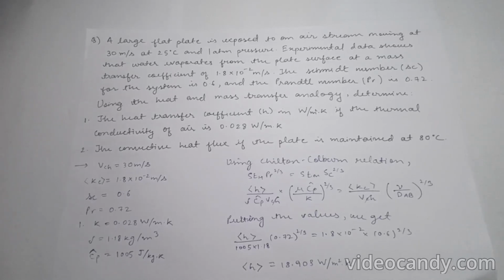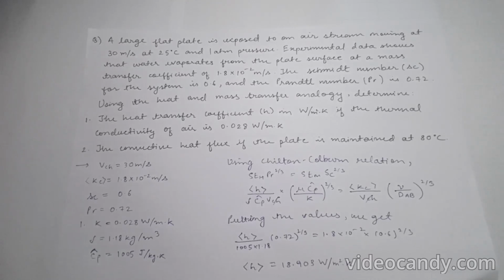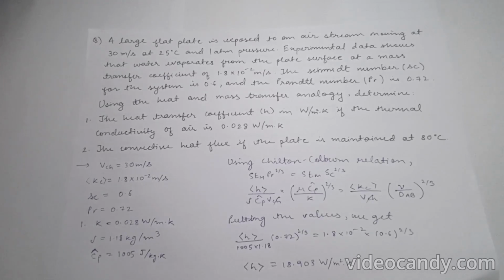In cases where the flow is not perfectly turbulent or the heat and mass transfer mechanisms behave differently, for example high temperature differences or significant changes in the properties of the fluid, the Chilton-Colburn analogy gives a more accurate representation of the relationship between heat and mass transfer.